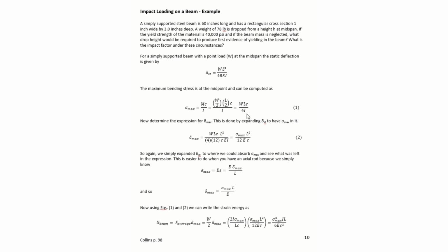To determine the maximum deflection, we compute the deflection based on our stress equation, and we get delta equals sigma max L squared over 12Ec.